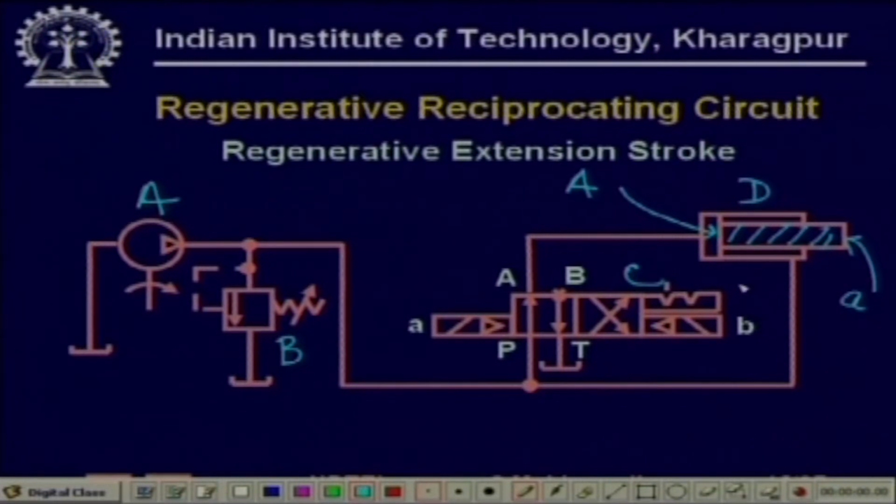Also look at this particular directional valve, which is two position, and it's detented in the sense that, what happens when both the solenoids are off? When both the solenoids are off, then it stays in the position corresponding to the last operation of the solenoid. So, if the solenoid A was on last, then even if you take A off, it is going to remain at the left position. That is due to a mechanical arrangement. So, that is detention. Okay.